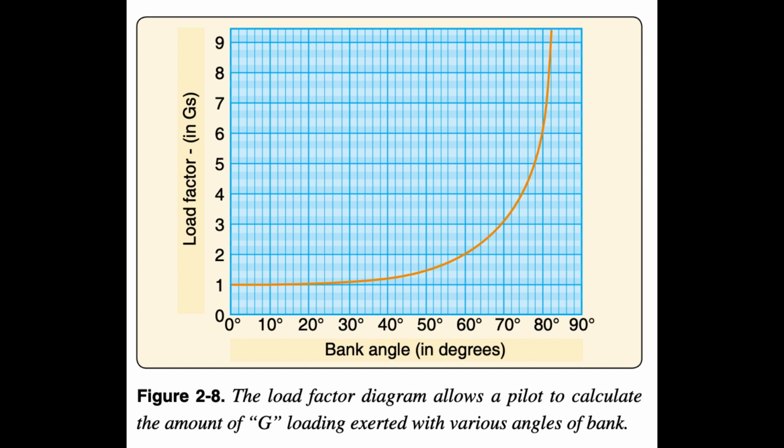It is important to note that each rotor blade must support a percentage of the gross weight. In a two-bladed system, each blade of the 1,600-pound helicopter as stated above would have to lift 50%, or 800 pounds. If this same helicopter had 3 rotor blades, each blade would have to lift only 33%, or 533 pounds. One additional cause of large load factors is rough or turbulent air. The severe vertical gusts produced by turbulence can cause a sudden increase in AOA, resulting in increased rotor blade loads that are resisted by the inertia of the helicopter.